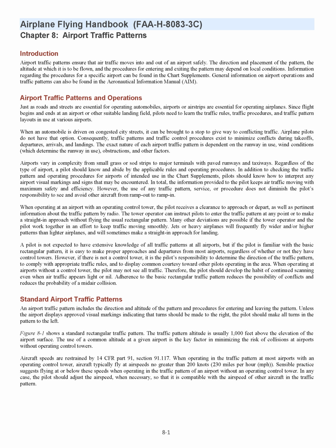When operating at airports without a control tower, the pilot may not see all traffic. Therefore, the pilot should develop the habit of continued scanning even when air traffic appears light or nil. Adherence to the basic rectangular traffic pattern reduces the possibility of conflicts and reduces the probability of a mid-air collision.